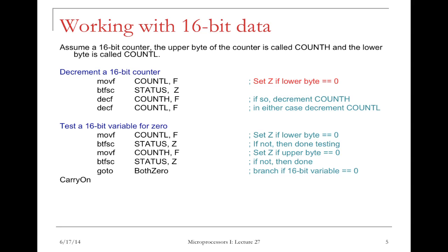So that's how we really get this 64, because we skip decrementing the high byte, and then we decrement the low digit. Because it doesn't specify which one is going to skip. It'll skip the very next instruction. Oh, okay. Yeah, it's always that.